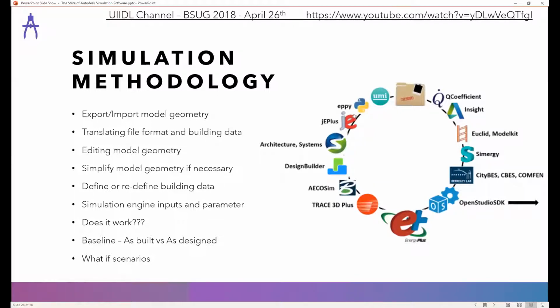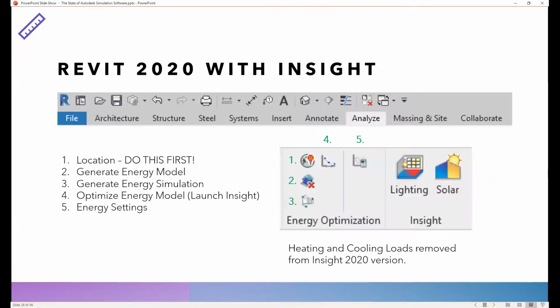And so then, once we've done all that, depending on the work, we propose what-if scenarios. Would it be feasible as well as economical to upgrade your T8s or T12s to an LED lighting system? If the client says no, they don't like the cost or the technology occasionally, then can we convince them to go to occupancy sensors? And what would that do to the lighting schedule and the reduction of the LPD and how much money they're saving? So that's kind of the lab's approach.